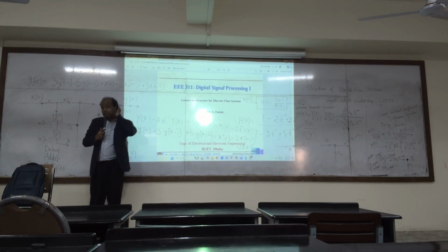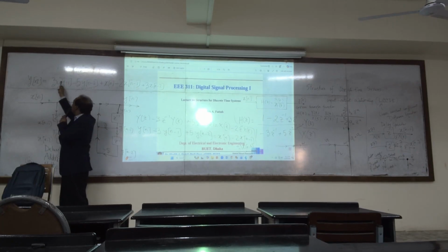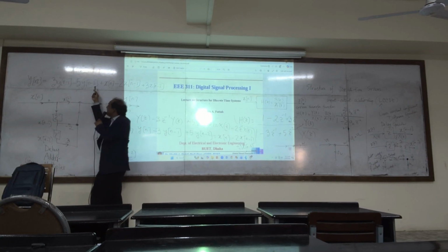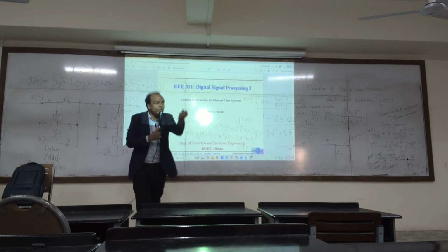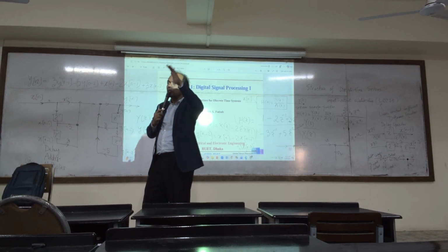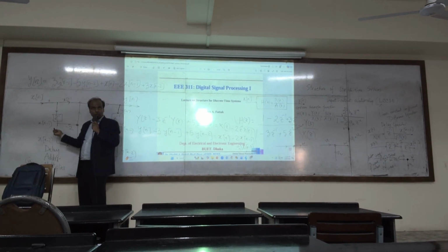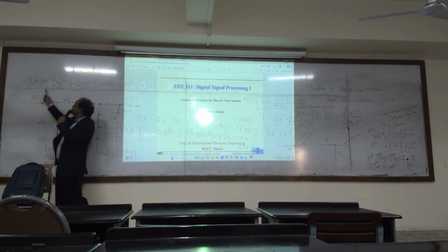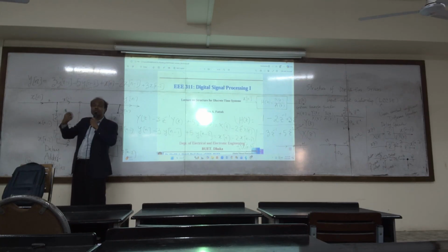I told you why. Because if you want an output y10, you need y9 and y8. These are previous instances, y9, y8. So who will hold these values? The delay elements will hold those values. So when you are here at y10, you need y9, 10 minus 1 is 9, so you need delay.